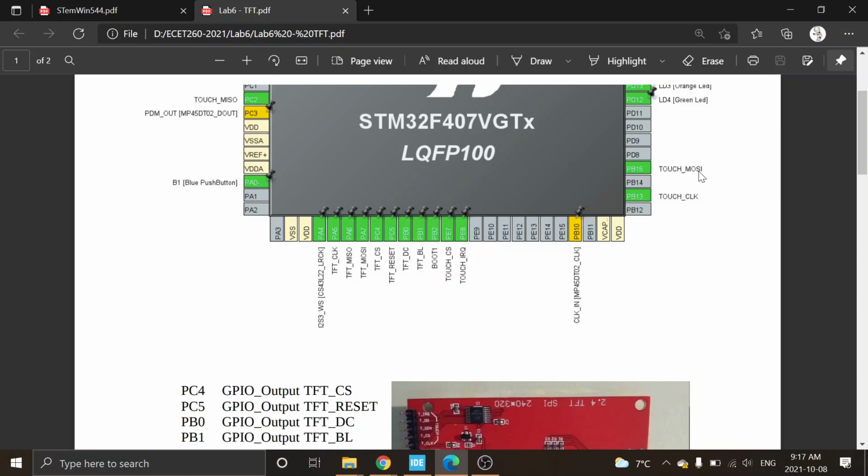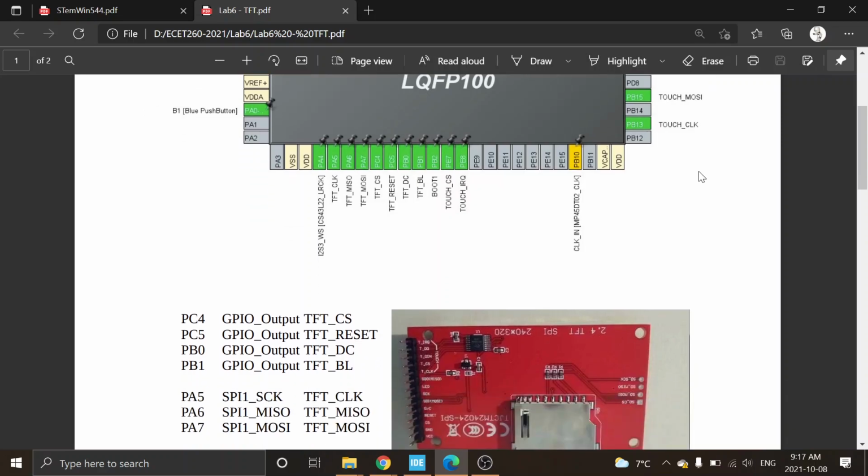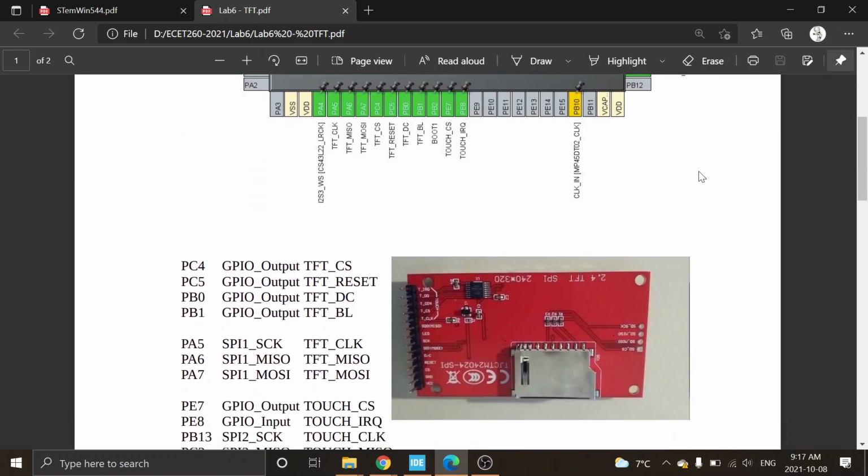The other thing that a lot of these boards have on them as well is an SD card reader. And so that's separate, and I didn't want you to have to go and wire it up. I have used them in the past, and those are wired there, and it goes to this card there. And your ARM board does support reading and writing. We pointed out that it has the FAT file system, so you can write stuff to directories on an SD card, for instance, so you could do data logging.